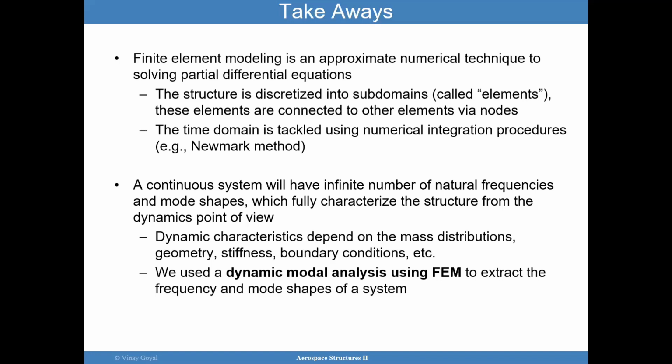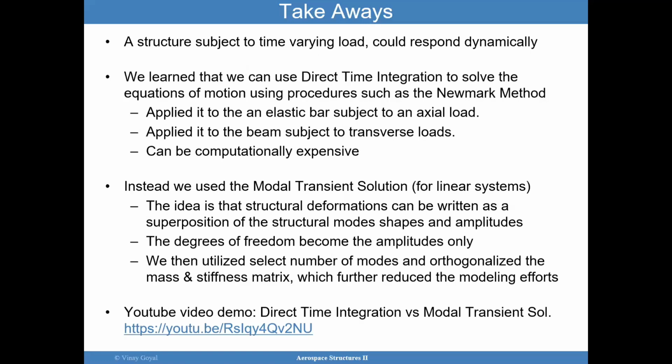We can use the dynamic modal analysis procedures in finite elements, like Pavel showed, to extract the frequencies and mode shapes of the system. So we can better understand how the structure will oscillate at a particular frequency, and what frequency it will be oscillating at. So how many cycles per second? We then covered the idea of